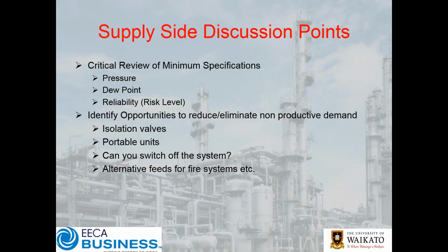Yes. Okay. So if that's the case, then generally, depending on how the towers are being regenerated, the purpose of that is you're going to sense your dew point, and then as the desiccant's no longer able to maintain the dew point, the dryer will then switch.